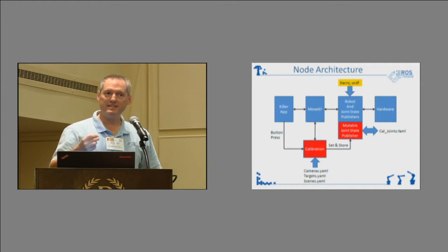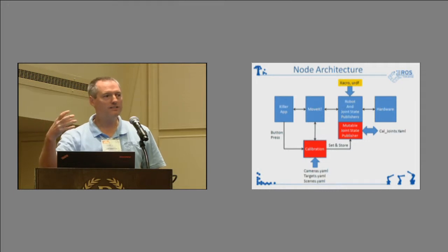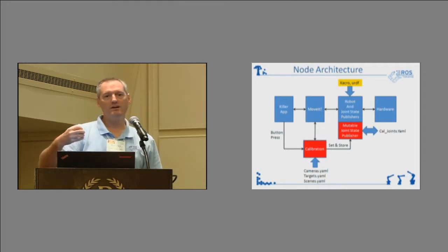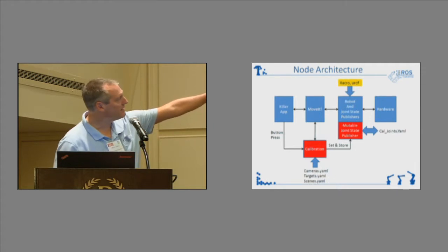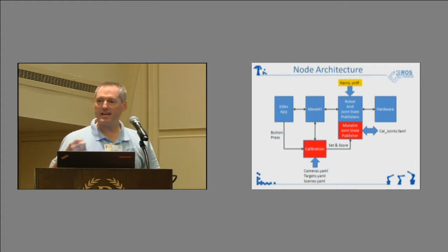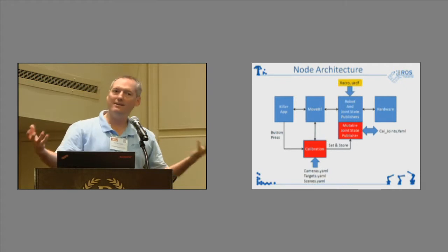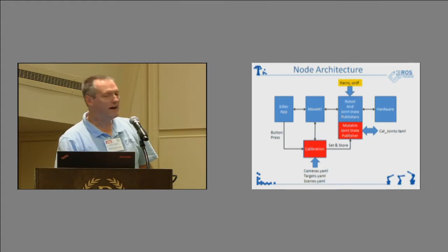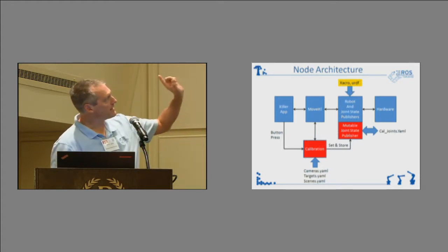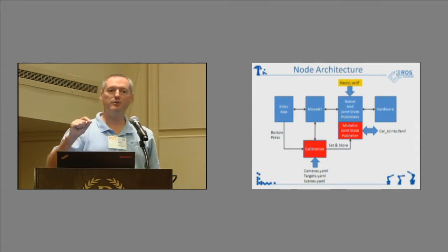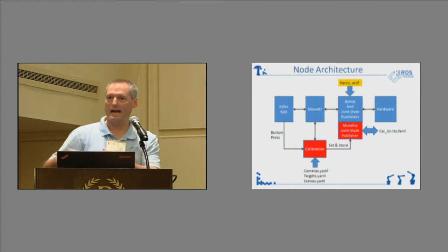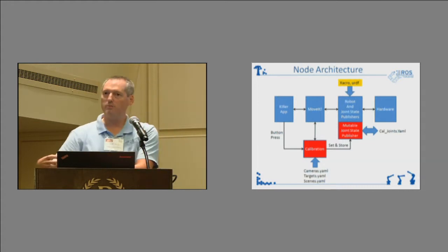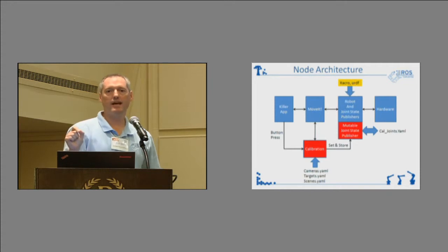However, all the items in those Xacro files, or your URDFs, for where the cameras are, are typically static. So how do you have your calibration routine, which are the things in red, change your model so that when you start it back up again, everything is essentially calibrated? What we have done is modify the thing in yellow, your Xacro file, slightly to replace every calibratable thing, like where the tower is that all your cameras are attached to, or where your robot is. We exchange every calibratable joint with a sequence of joints.